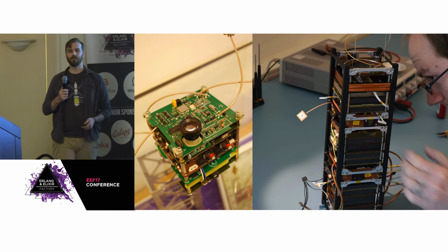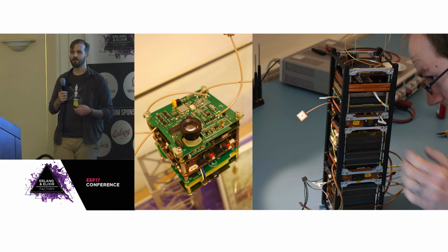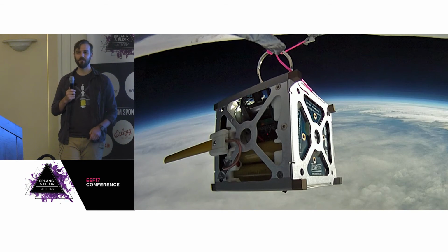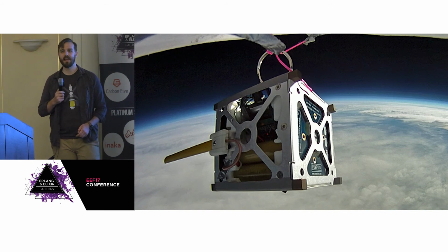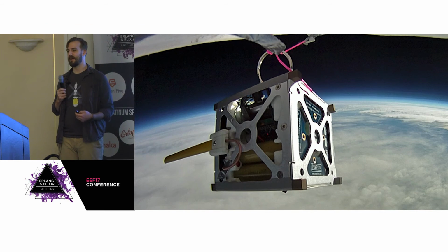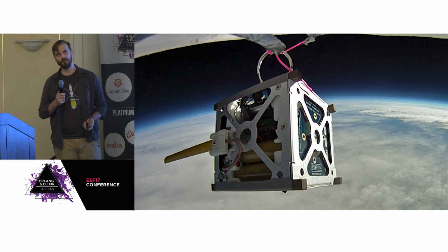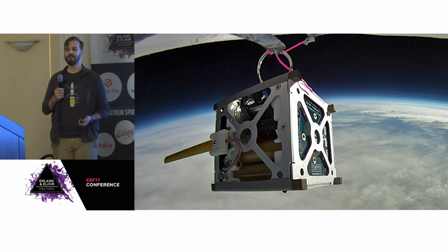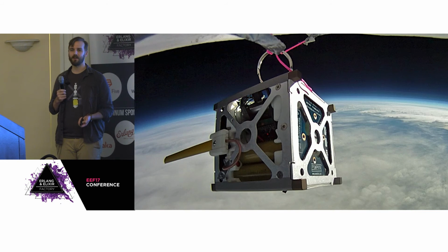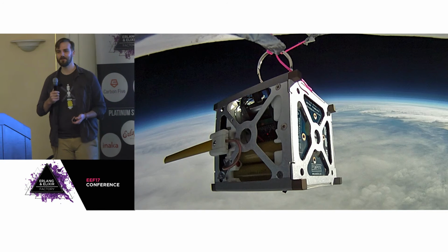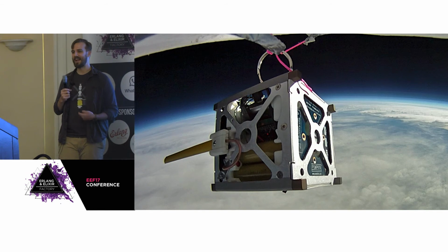The other neat thing about CubeSats for private organizations, it's off-the-shelf hardware, so they're easier to program. Because they're so light, you can test them in production by sticking them on the bottom of a helium balloon and lifting them up out of the atmosphere. And you get a sense of how your batteries will behave. One of my favorite defects is when people put a lithium-ion battery up that isn't space-rated, and they expand and then pop the housing, and then your CubeSat flies apart. There are a couple images of that happening